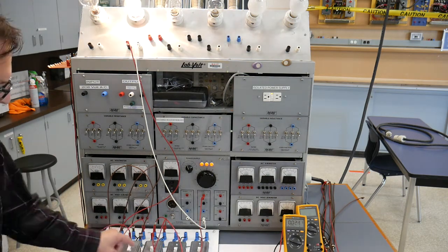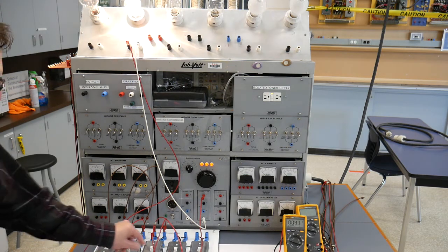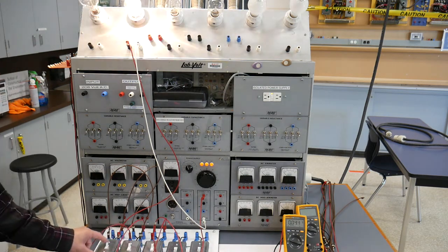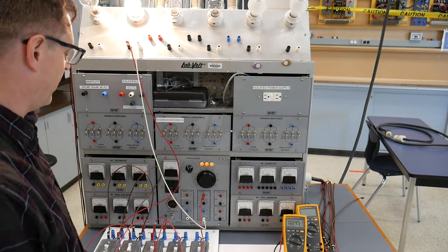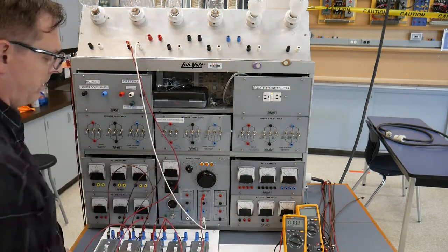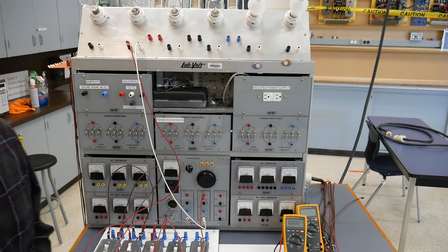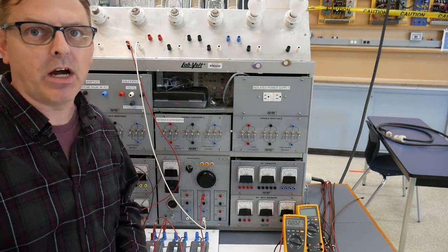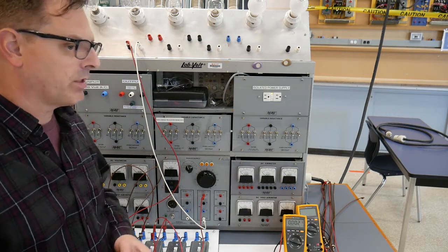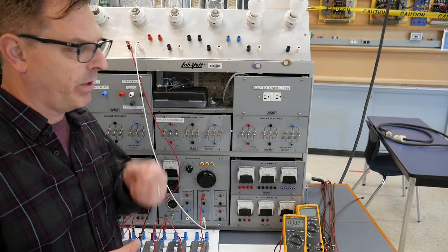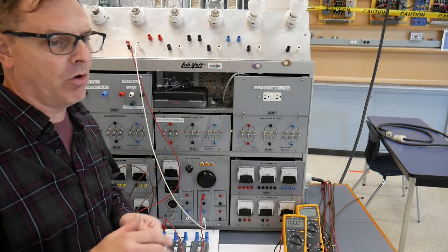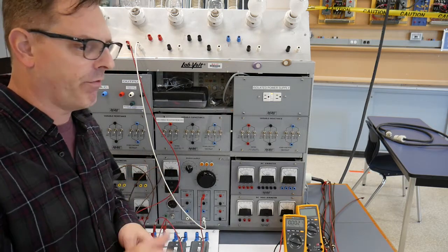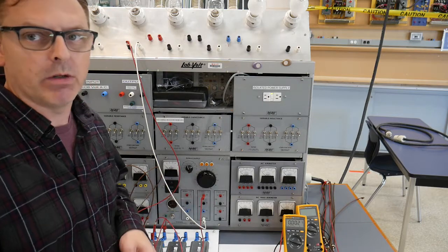The best way to check these is always to pretend like you're moving through the house. So I now have a perfectly excellent working 4-way switching circuit. Okay, if we wanted to add more 4-way switches to it, we could do that at any time. In other words, if we wanted to switch a single or a bank of lights from more than 3 locations, we just keep adding more and more 4-way switches in between the 2 3-ways.